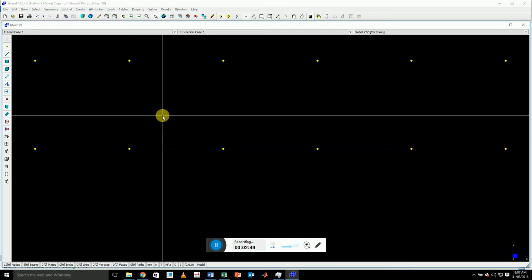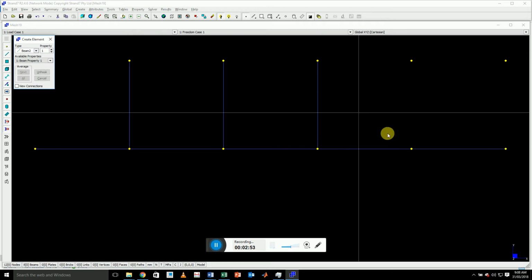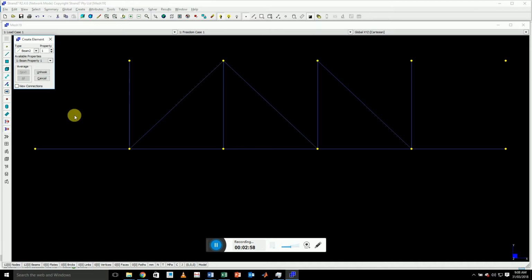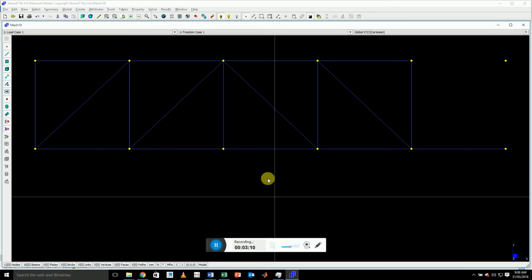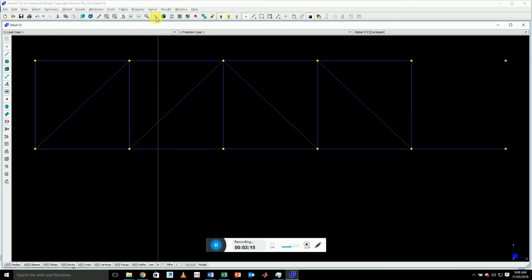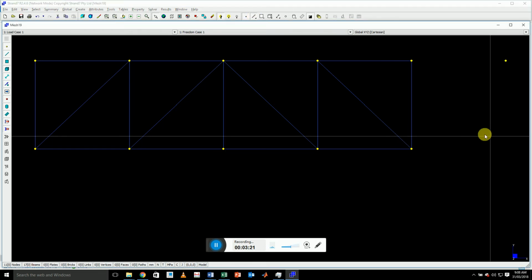And now I'm going to create my remaining elements. I made too many. Remember, we never want to do this, okay? We never want to join to there. We've got to join all of the bits up. Cool, we have all of our elements. I made one too many by accident. If I go back to select and make sure I'm on beam select, I'll be able to grab that beam, hit delete, it'll go away. So the node, but that's fine.